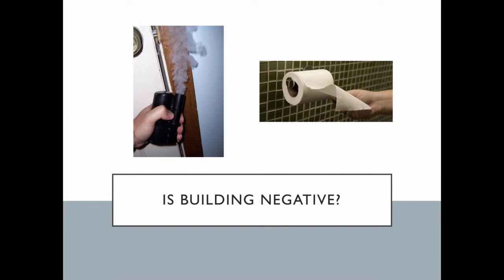On one particular job we went to, they were having a negative condition, and it was because the makeup air was tripped on the freeze stat, and they still had the exhaust fan running, so it's pulling the whole room and whole building essentially into a negative, and flue gases were coming out and overcoming the people in the facility.